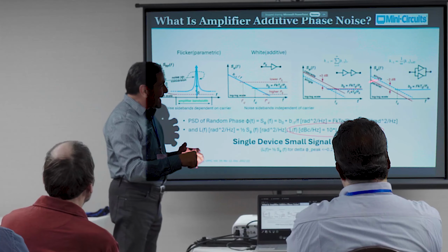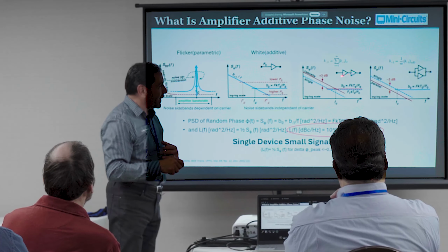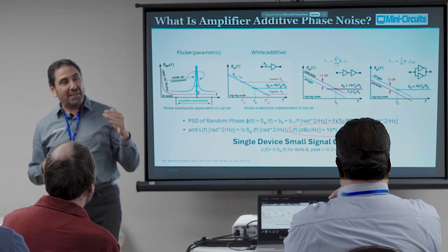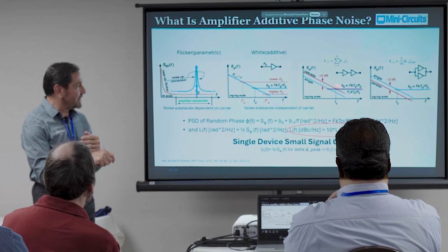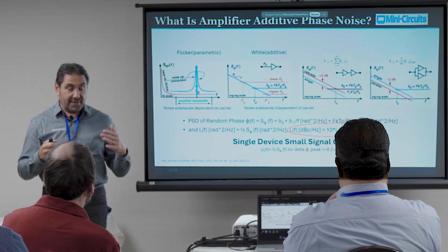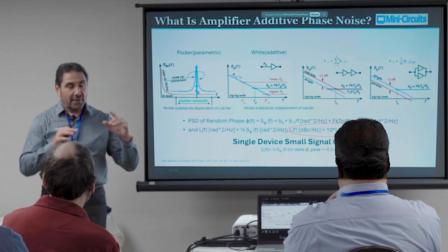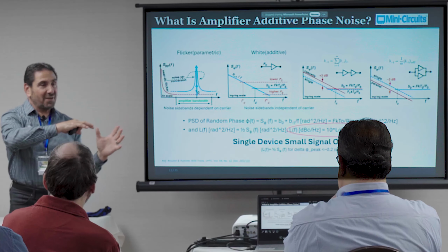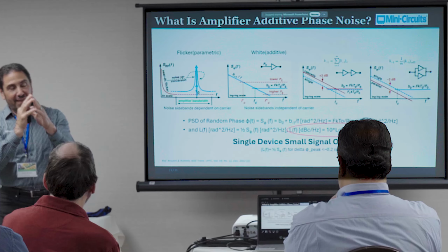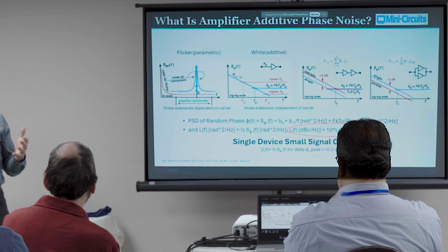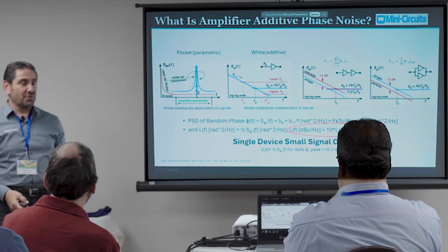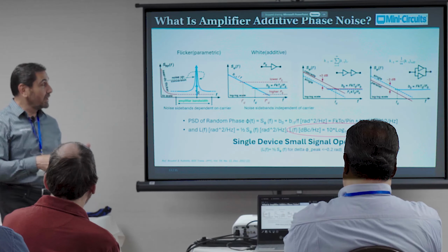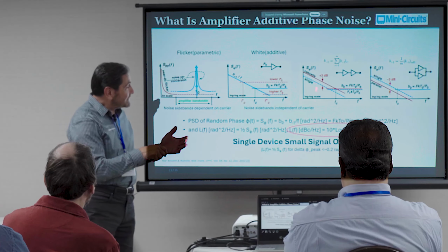Then we go into just some cascaded theory. Again, we talked about this earlier, where the 1/f noise will add as a power. It adds 3 dB log base 2 of n, where n is the number of stages, or m. And why is that? Again, you can see you have your perfect tone. You put it through the amplifier. The 1/f noise is parametrically upconverted to that carrier. That goes through the next stage. Well, how do those noises add? They add using power addition. So it's like the square root of v squared 1 plus v squared 2, as opposed to the parallel case. So that's why it's 3 dB.